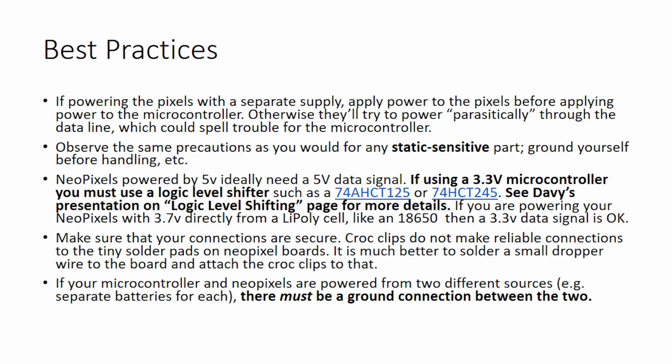And that'll probably blow the I/O pin of the microcontroller. So for that reason, it's better to power the NeoPixels before you power the microcontroller, or have the microcontroller come up and put all the pins that have got NeoPixels on.